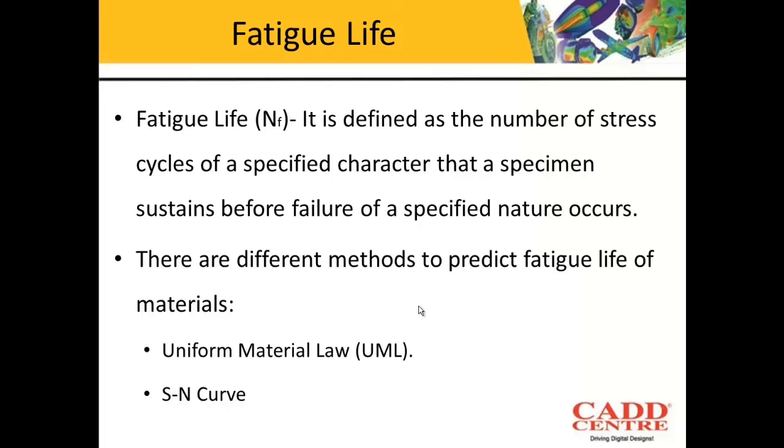Now what is fatigue life? Fatigue life, which is denoted by NF, is defined as the number of stress cycles of a specified character that a specimen sustains before failure of a specified nature occurs. In simpler words, it is nothing but the life cycle of a model, of a material. Now to calculate the fatigue life, there are different methods.